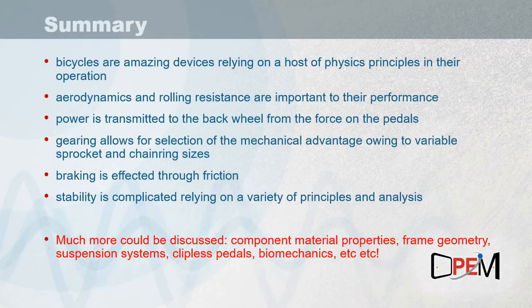In talking about the force transmitted to pedals, we took sort of a simplistic case of pressing downwards when the pedals are horizontal, but of course you can transmit much more power on average to the back wheel if you're able to put force on the pedals as they go all the way around in their circular motion. This is partly helped in the 21st century by clipless pedals that were first introduced in the second half of the 20th century.